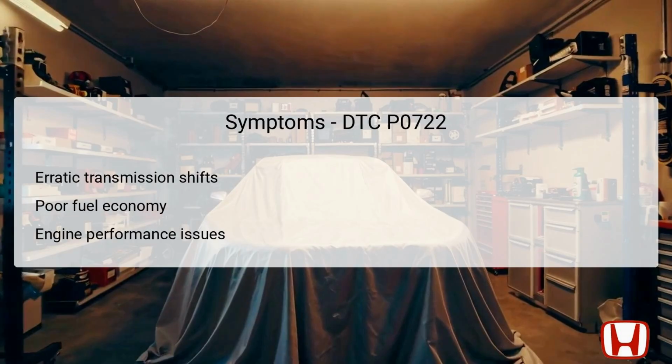Additionally, you may observe general performance issues with the engine, as the lack of proper input from the sensor causes the PCM to make incorrect adjustments to engine operations. Here, it's vital to pay attention to both subjective driving experience and the diagnostic codes when troubleshooting, as these symptoms give valuable clues about the underlying problem.